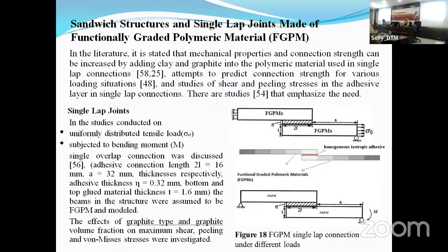That was related to the plate, and that was related to the beam. Look at that. It's a single lap joint. It's a basic adhesively bonded joint, and we can subject it to a tensile load, and we can subject it to a bending moment.